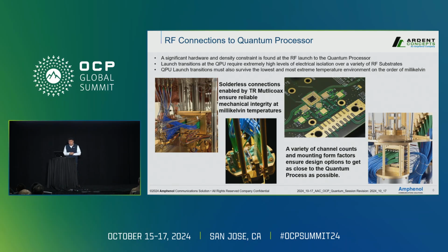absolute zero. To tackle the electrical and the cryogenic challenges, many quantum engineers have embraced solderless compression mount connector technology. This innovation provides a solder-free and electrically compliant connector and launch transition, ensuring reliable mechanical integrity in the most frigid millikelvin environments and through multiple thermal cycles as well.